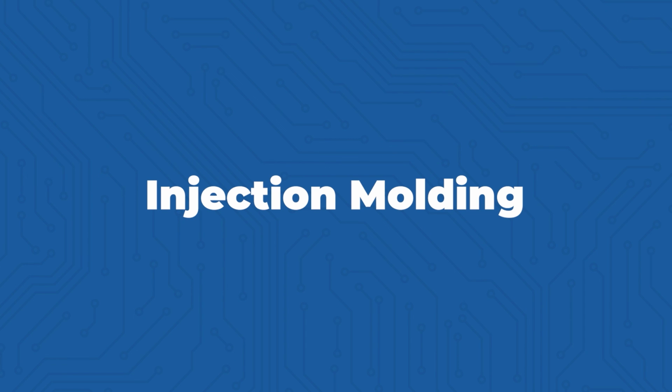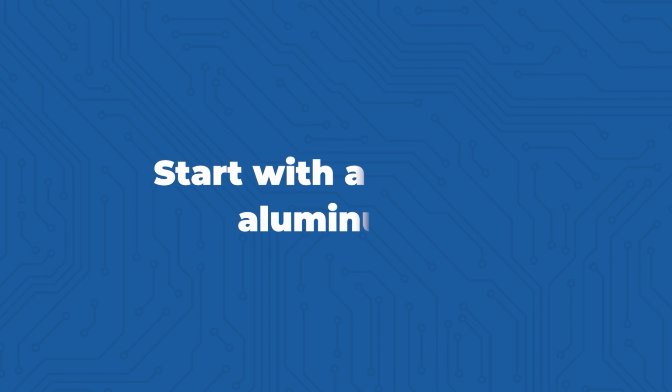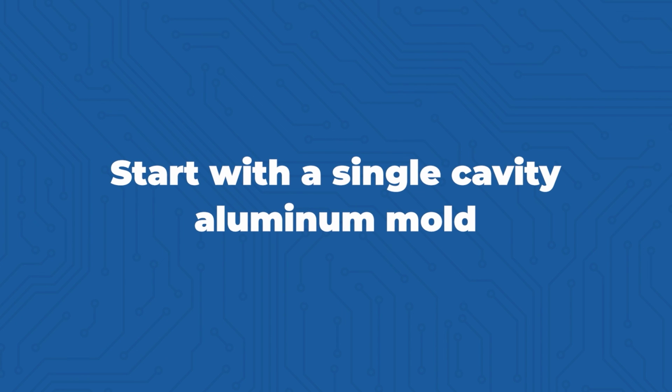And once you do switch to injection molding, as I always advocate, start simple and then take small steps up from there. For instance, start with a single cavity aluminum mold once you're ready for injection molding. A single cavity just means that mold makes one copy of your part each time it's injected with plastic. That's the simplest you can do, just having a single cavity or one cavity.